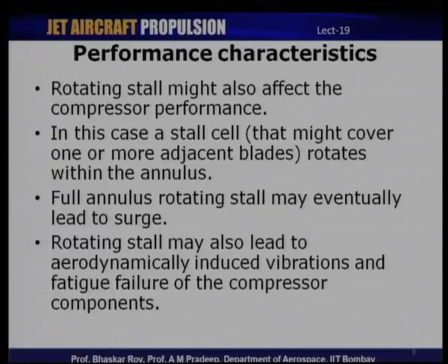What basically happens is that if one or more adjacent blades are undergoing stall, the stalled cell will rotate within the annulus, and if allowed to grow, these stalled cells might propagate and affect the entire annulus, eventually leading to surge. Rotating stall on its own can lead to aerodynamically induced vibrations and eventually fatigue failure of the compressor components.